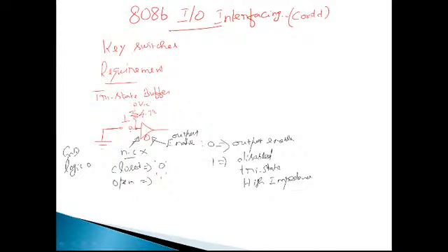And when the switch is closed, this 0 will be connected to here. You might ask, VCC is already coming, sir, what will happen? When the VCC is connected, what happens if the switch is closed? The current from the power supply will flow like this and drain here. So essentially this particular potential will become zero volts. When it is 0, it is a logic 0. That's the basic idea. So when the switch is depressed or closed, logic 0 is applied as an input to the buffer, and when the switch is in the open state, logic 1 is applied here. So that's how we are now doing it.